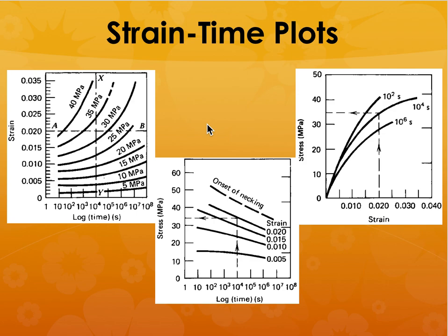So you have families of plots such as these. They are often a necessary design input for polymers. And isochronous, isometric, etc. Isochronous is at the same time. If you are pulling these materials at a certain rate, say at 40 megapascals per minute, it will show a certain behavior and a certain amount of strain.